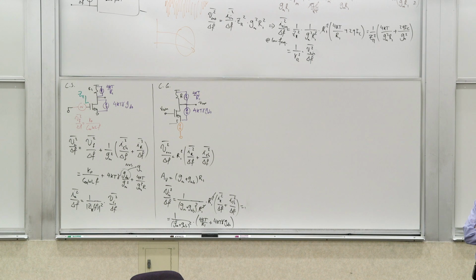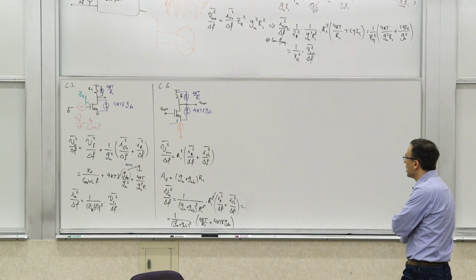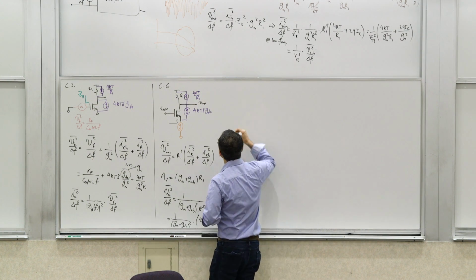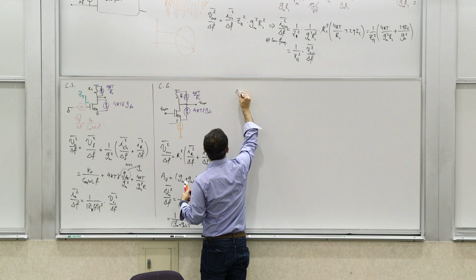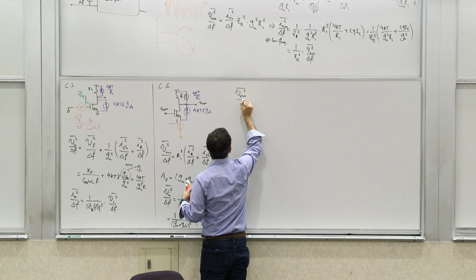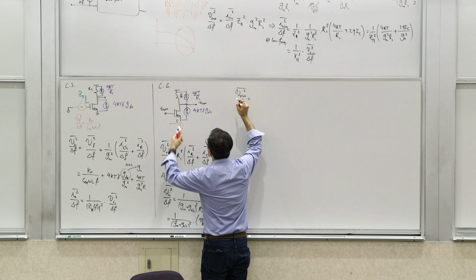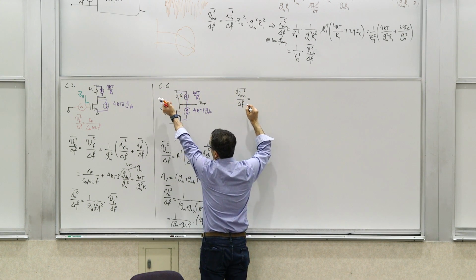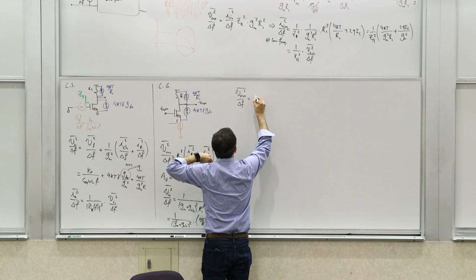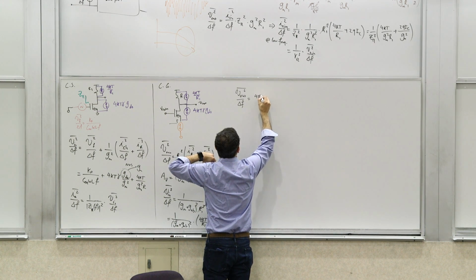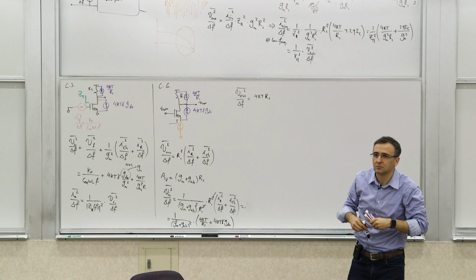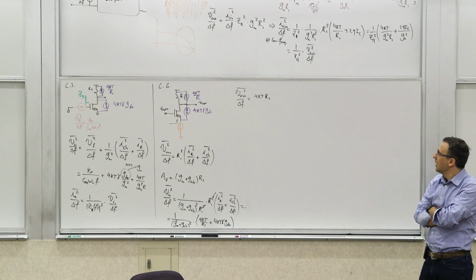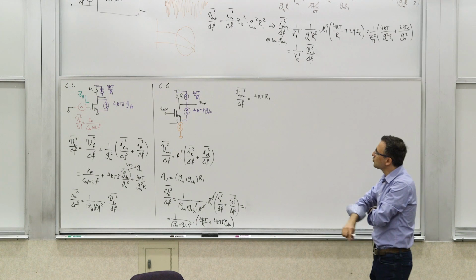The resistor part of the noise is obviously the same. So this is again V out magnitude squared over delta F. There's a current noise injected into this resistor, so you get basically 4kT R1. That's what you have. Now, what happens to this noise source?